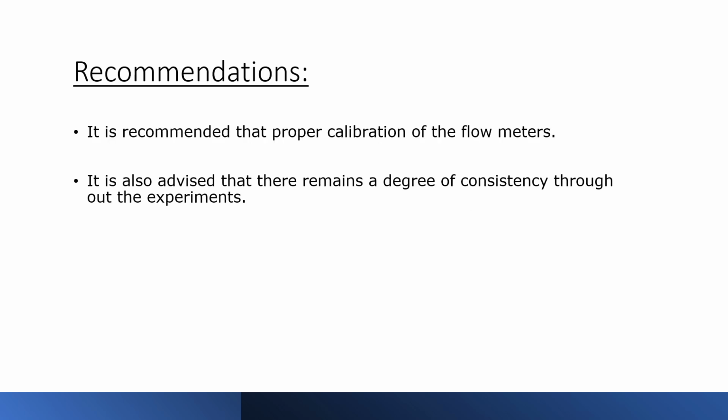Recommendations. It is recommended that proper calibration of the flow meters is required before proceeding with the experiment to ensure proper comparisons between the different devices. It is also advised that the person taking the readings from the devices remains constant for all the different flow meters. This includes the person that is operating the stopwatch.